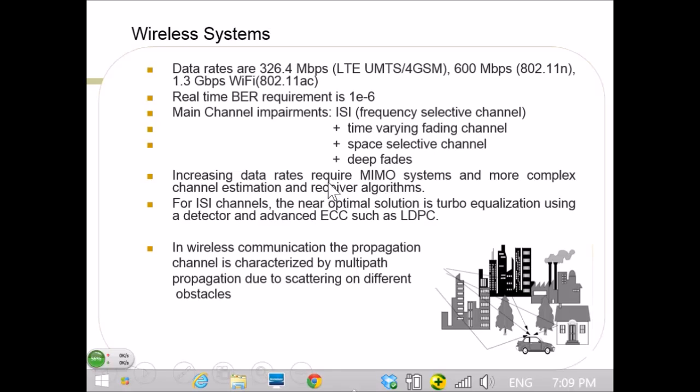So basically for the wireless, in one sense, the algorithms we use are actually more complex for the MIMO as compared to the hard disk drive. The hard disk drive complexity is only just the turbo equalization, right? But here, in the MIMO, you have much more complexity even before doing a turbo equalization. So there are more digital signal processing algorithms you have to do. But in the hard disk drive, the signal processing you have to do has to deal with doing some analog equalization, doing some DFE and so on. But in the case of wireless, you have a lot more things that you need to do.